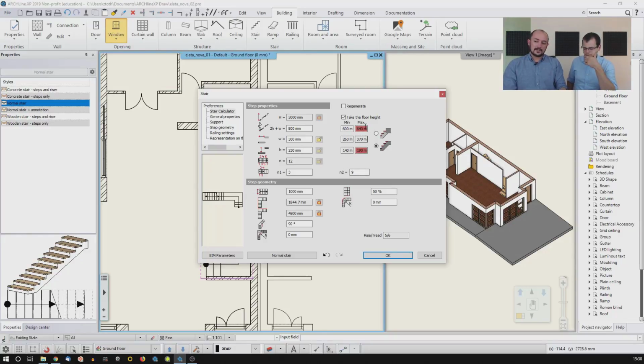And if there is a red value, that means based on the current local standards, this stair with these specific settings is not that ergonomic, so you need to fine tweak that. Actually, you can still place it on your drawing because this could be a surveyed stair, but it's a kind reminder that you need to change those values if you'd like to make an ergonomic staircase.